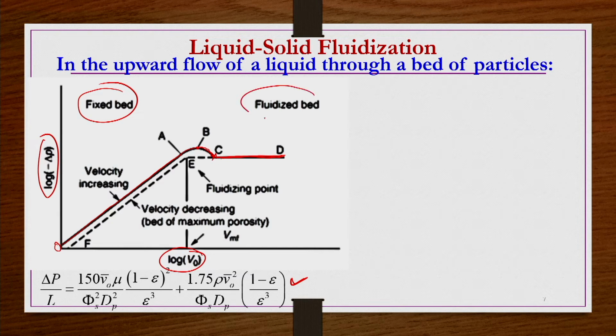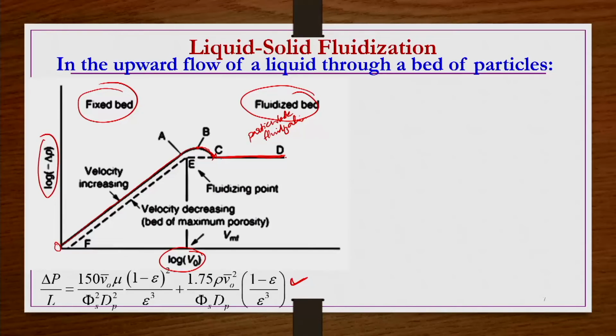So, this is a kind of fluidized condition, and we are talking especially about liquid-solid fluidization. So, we can say it is a kind of particulate fluidization, right, where the bed uniformly expands, and the bed density is going to be the same at different locations within the column, wherever you take it within the expanded bed. So, the pressure is going to be the same.